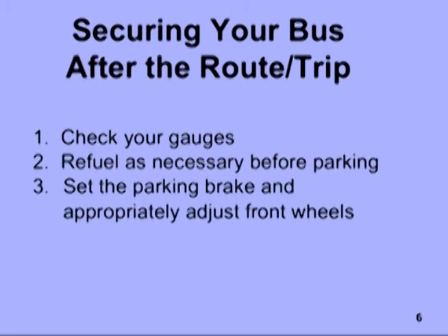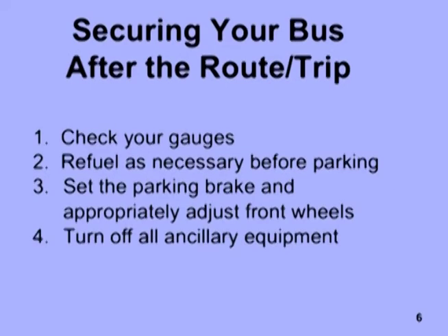Set your parking brake and appropriately adjust the front wheels of your bus. When parallel parked next to a curb, turn your front wheels away from the curb when parking on level ground or on an upgrade. Turn them toward the curb when parking on a downgrade. When parking in a parking space parallel to other buses, leave your wheels straight. Always set the parking brake.